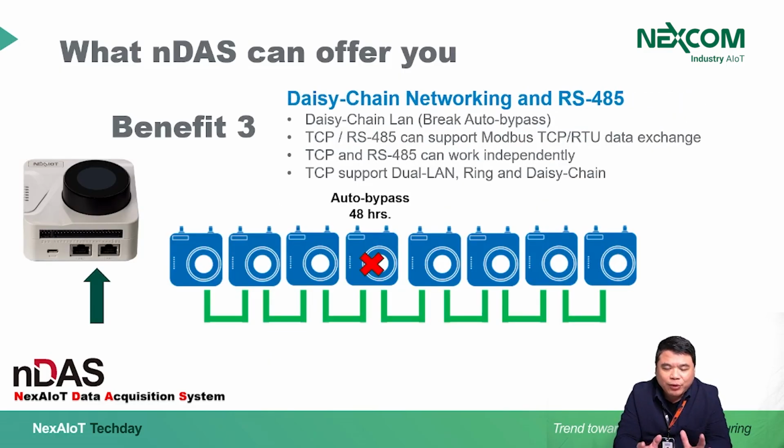And this one is the hardware spec. This one is very important. We support the daisy chain. Daisy chain means, as you can see in the picture, traditionally you need a switch hub, like star wiring, but now you can see in the picture it only bypasses. And we know in the field your cabling cost may be expensive due to the length to the module, so you can save your cabling cost.